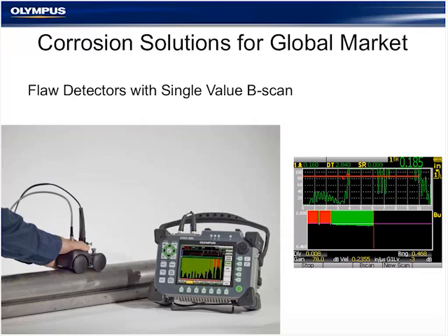So it does give you essentially stripe measurements of your pipe, and you can get a profile of that section of pipe to give you an idea of what level of corrosion you're dealing with. Now, if you have a pipe that might have some sediment in the bottom, oftentimes this buggy might be run along the lower portion of the pipe to give you an idea of where it might be the thinnest.